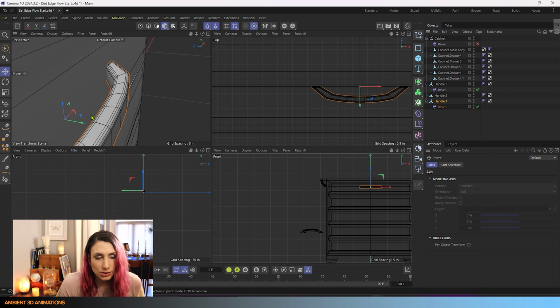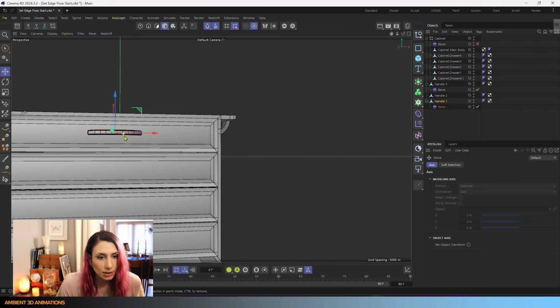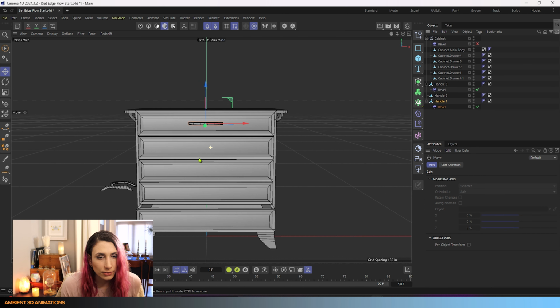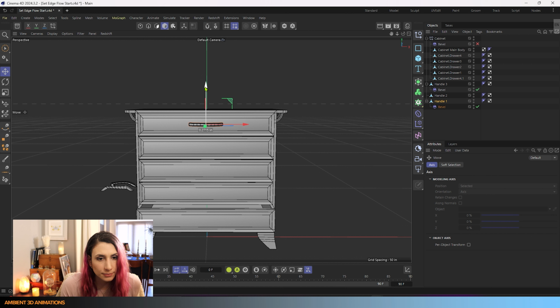Now we're going to need to have this for each. Going to turn off the snap here for a moment. This looks pretty well centered. I'm going to hold down Control in order to duplicate this while holding down Shift while I move it in the Y direction. And you'll see we're actually snapping to increments. So I can snap this to 4.5 inches and it's centered in the next cabinet because that's 4.5 inches down.